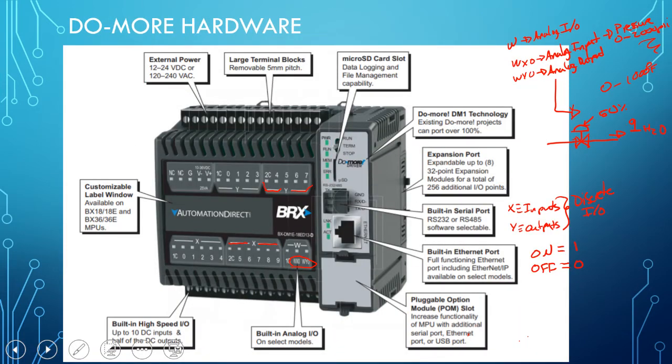So 50%, instead of on or off, opening 100%, which is this, or 0%, you want to open it 50%. So you send a signal that is proportional to the opening and closing of the valve. So those are analogs, right? So all these are analogs. We are not covering this yet. We will, but we will cover discrete inputs and outputs.